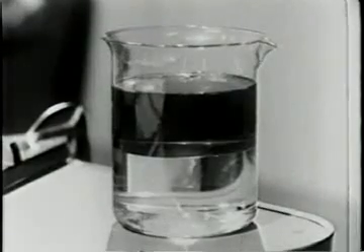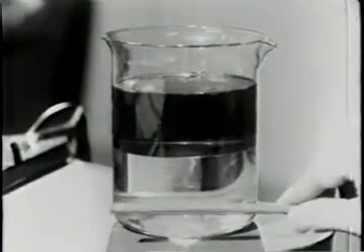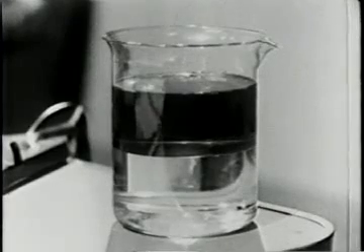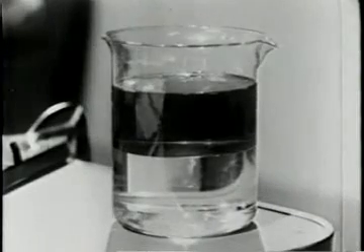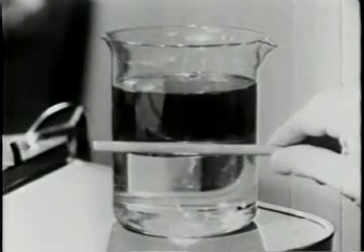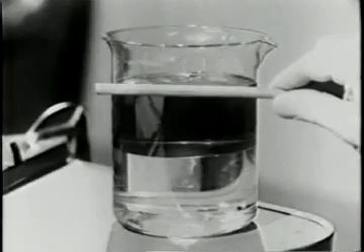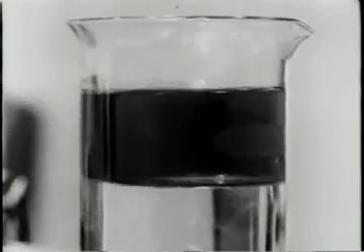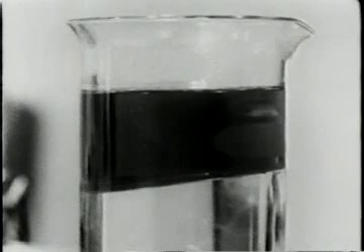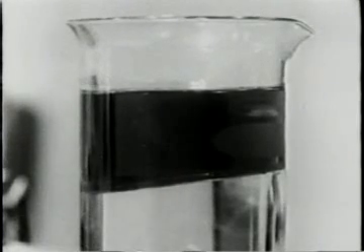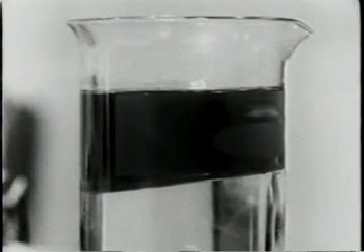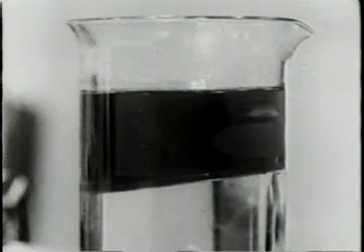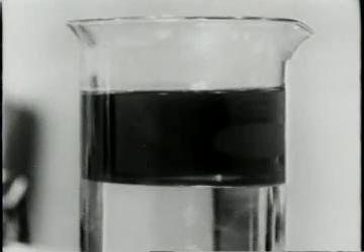In a fluid at rest, the lines of constant pressure are horizontal. Since the circulation is forever zero, the lines of constant density must coincide with the lines of constant pressure. That is why the interface and the free surface are also horizontal. If we tilt the interface, it does not remain tilted, as it does in this photographic illusion. The constant pressure lines and constant density lines are now misaligned, and the pressure forces in Kelvin's theorem create a circulation which rectifies the situation.